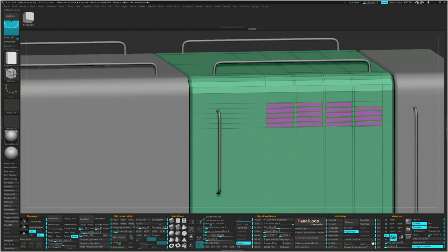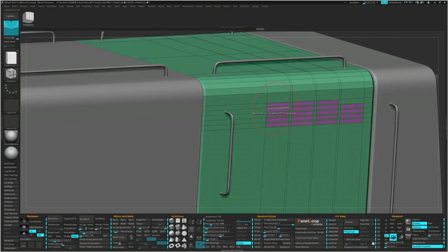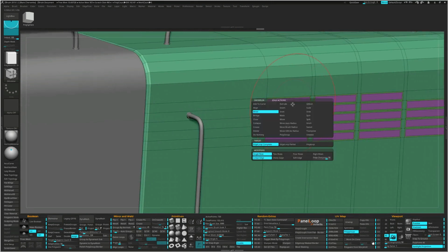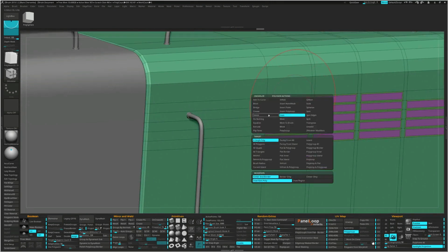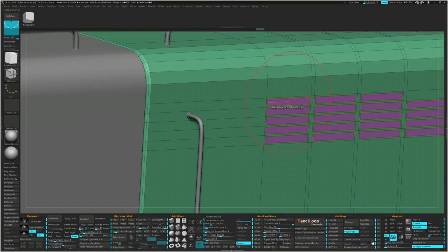Next we want to extrude an edge. So in Edge Action, click Q-Mesh. Make sure you click Do Nothing in the Polygon action so we can use the polygons to control our edge extrusion better. When hovering over a poly, you will see an orange line. Make sure that is pointing to the edge you want to extrude and drag out. Click to repeat.